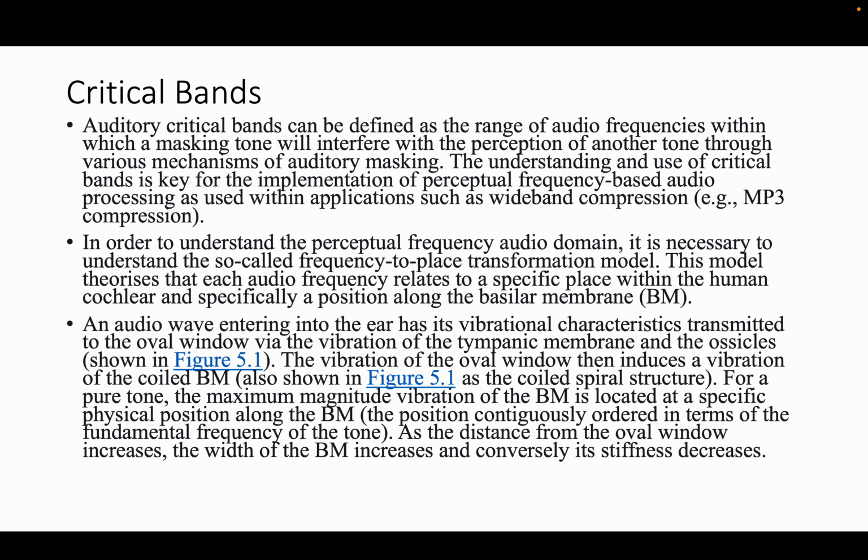Critical bands. Auditory critical bands, in speech processing and audiologist language, are defined as a range of audio frequencies within which a masking tone will interfere with the perception of another tone due to various mechanisms of auditory masking. The understanding and use of critical bands is key for implementation of perceptual frequency-based audio processing used in applications like wideband compression, including MP3 type files.